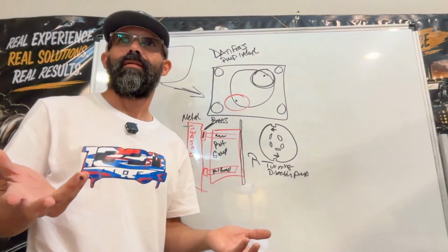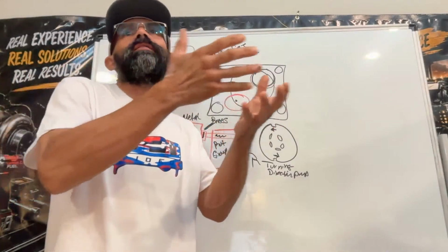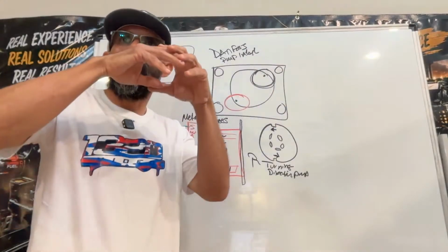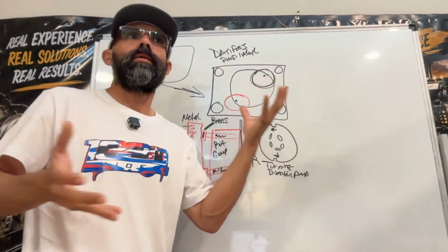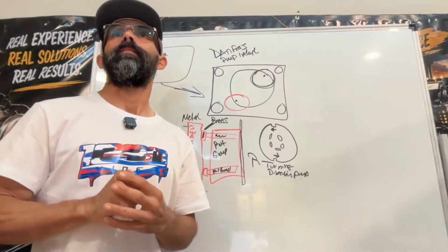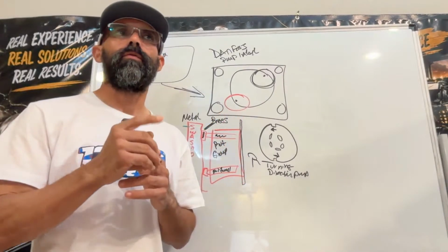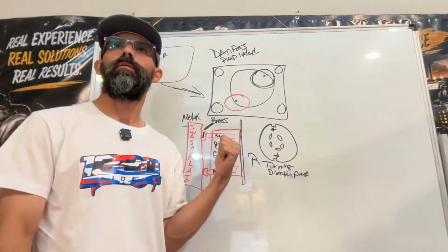What? Go through the whole system, go through the whole process, identify why it failed, open the whole pump, inspect every single piece, every single component, and be like, okay, everything is here, intact. And ask yourself, what caused this pump to fail?